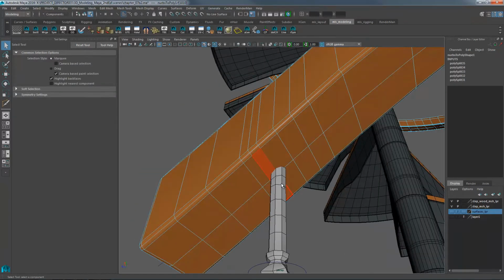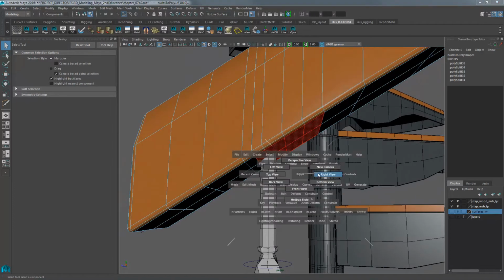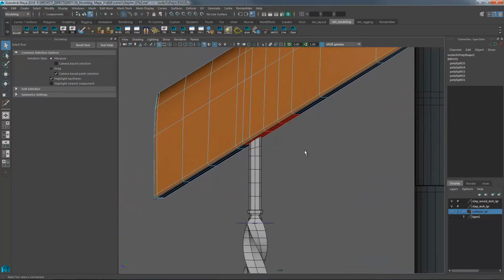So from here, holding tab, I will take this selection. That seems to be a good selection. And because we're instantiating this stuff, it doesn't really matter if I get the exact length correct right now, because once I see all 5 sitting next to each other, then from there I can make adjustments, and then as we instantiate all the way up, everything will be spaced out nicely. So as long as I get these 5 evenly spaced, everything else will look good.